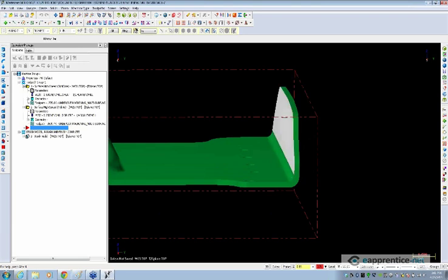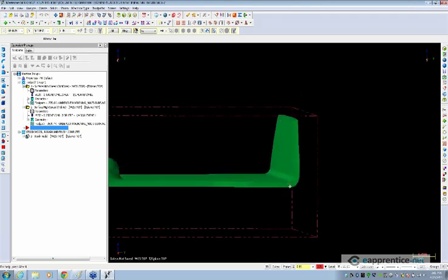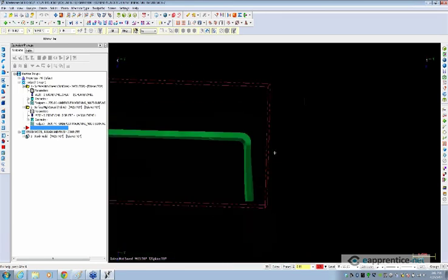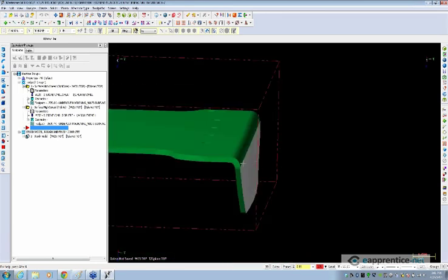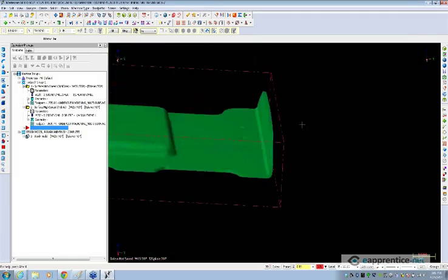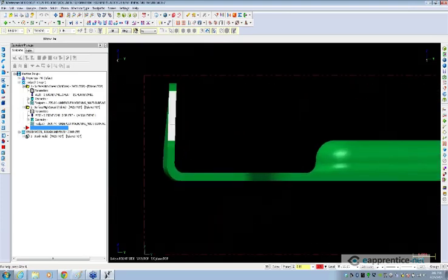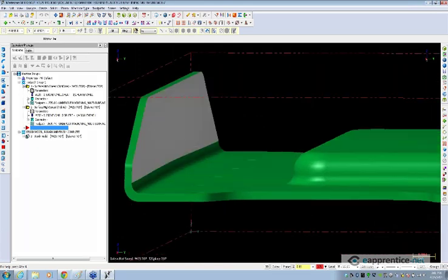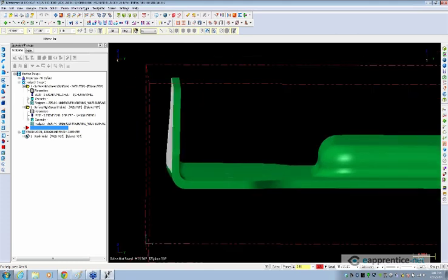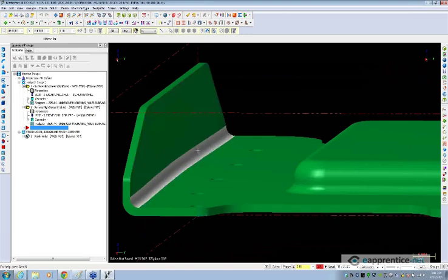And it's open because I can machine it from this side, from the top side, but then I can also flip the part over and still get access to this wall. So if I machine it from two sides, I don't have to do any undercutting. If we look at this left wall, however, this has what we refer to as a closed angle. So on the inside here, we have this wall that tips in, and in order to cut it, we have to cut it from the top side, and we have to do some undercutting.